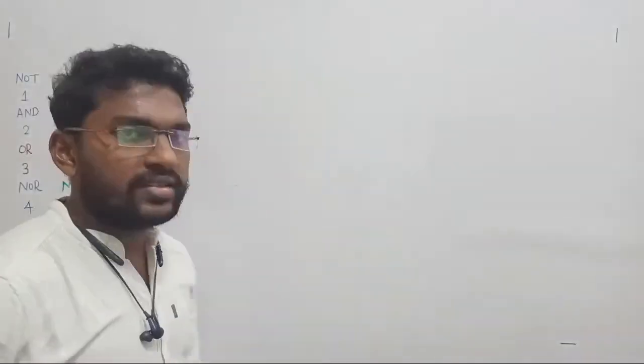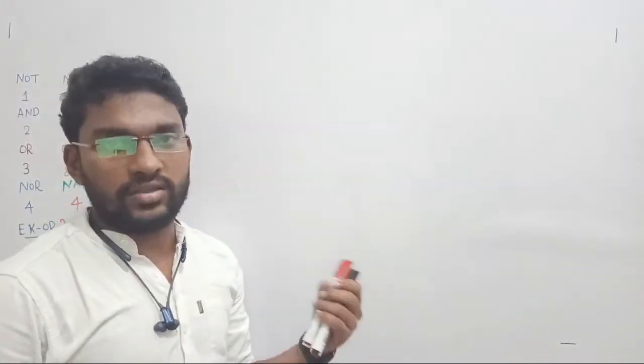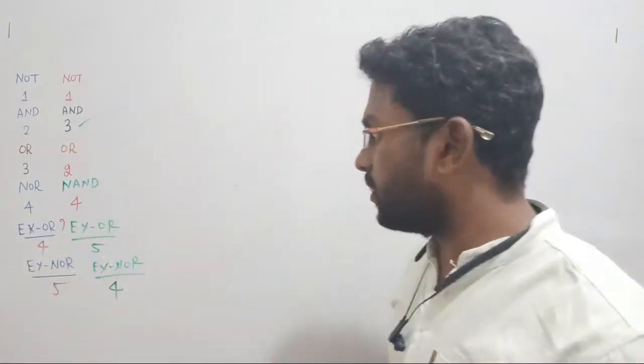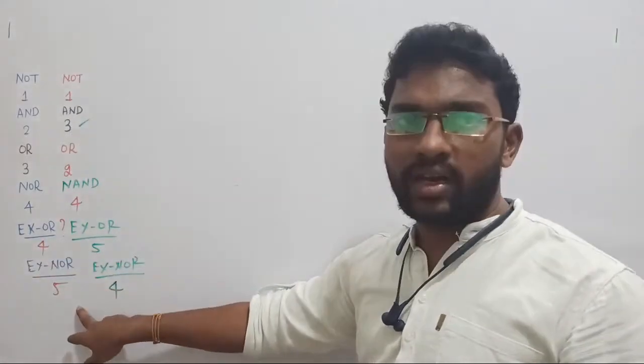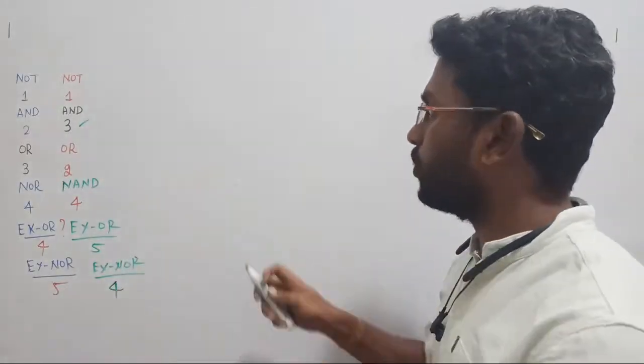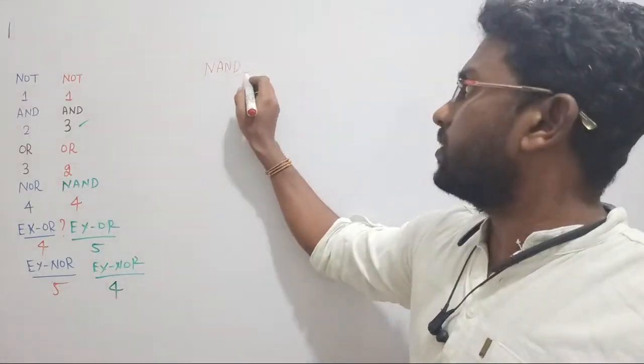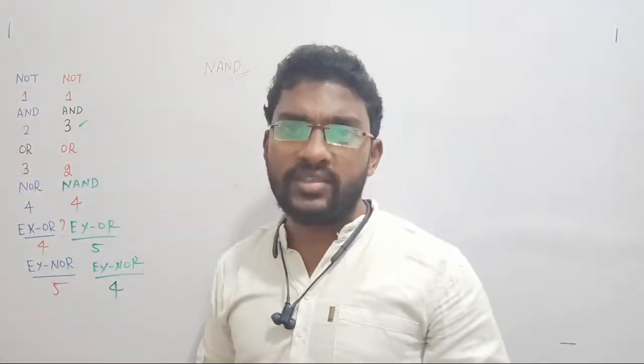Fine. So that is how we are realizing various logic gates, right? I hope things are very clear to all. Guys, one small task. Just take your XOR gate and XNOR gate and realize them with the help of NAND gates once again. Cross check it by yourself. Let me correct it. That's all. Clear? So this is all about the basics of logic gates.